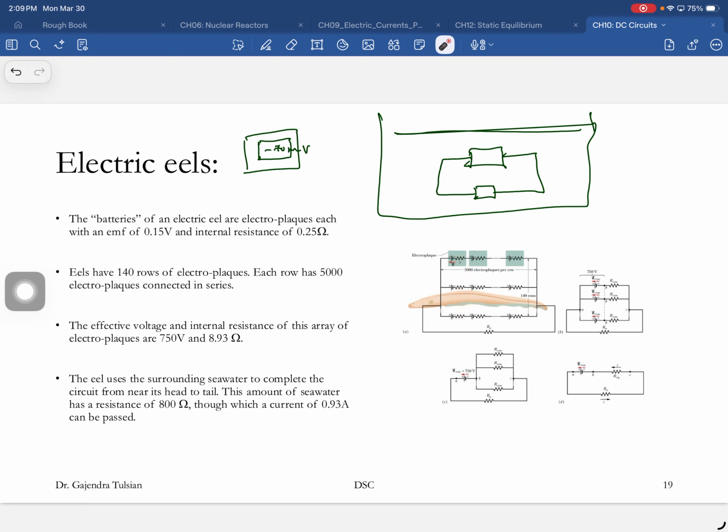So to prevent the current passing through you to the ground, you connect the casing to the ground. Current uses the path of least resistance. It'll go to the ground rather than through you to the ground. So that's what the third prong is. The casing is connected to the ground. Of course, if your hands are wet, you're decreasing the resistance through that path.